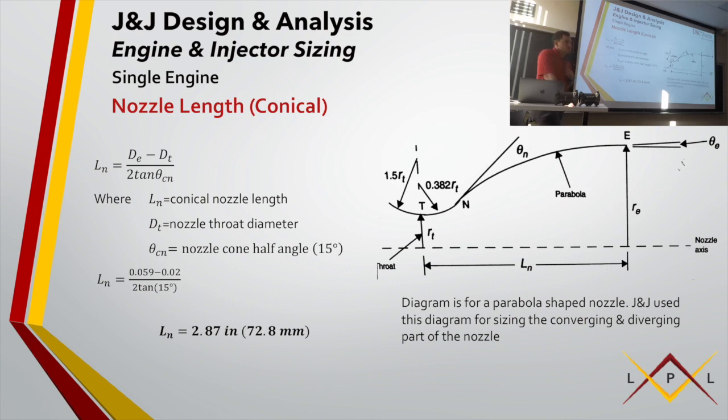So how do you determine where you start the radii? Oh, they're all general drawing. So that's like if you have an imaginary circle, what the radius would be. But I mean, when you do your sketch in NX, if you make all the lines tangent to each other, that's the only kind of solution that it sits on. And you would define your throat and your exit and your angle, and apply everything, and then it's like one solution.